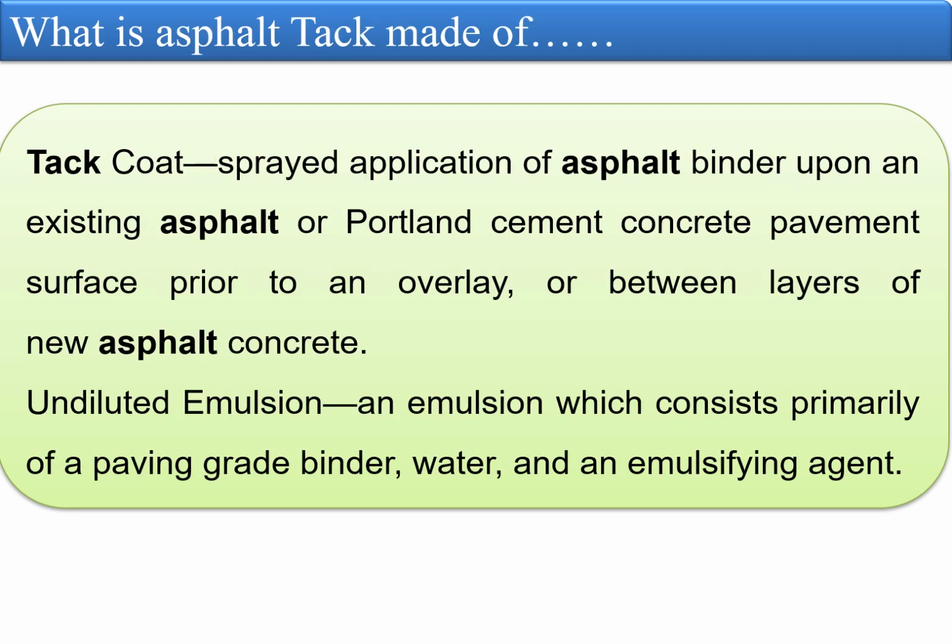Tack coat is a sprayed application of an asphalt binder upon an existing asphalt or a Portland cement concrete pavement surface prior to an overlay or between the layers of the new asphalt concrete. This is the meaning. Asphalt tack coat is made up of undiluted emulsions, an emulsion which consists primarily of a paving grade binder, water, and an emulsifying agent.